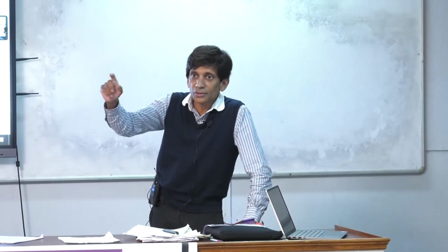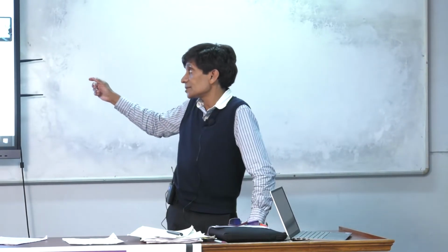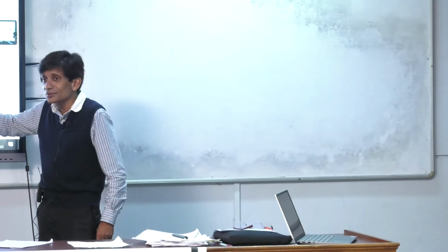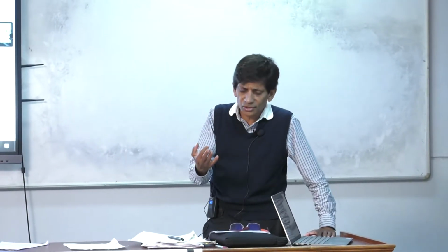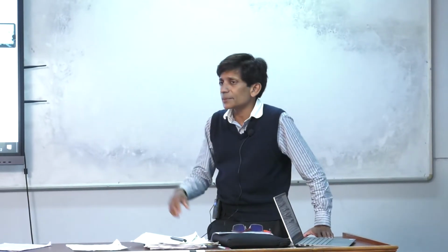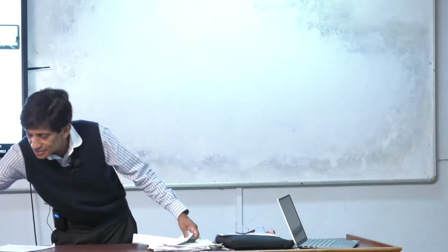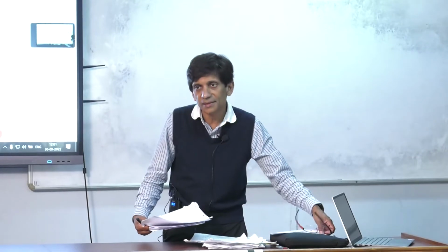Mass balance on the overall system, mass balance on one of the phases. You could have done a mass balance on the dialysate instead of the blood. It's more complex though because the dialysate you're trying to calculate things there. So it'll become mathematically more complicated, but you can do it, okay? And then you solve three simultaneous equations and you come up with the numbers, okay? So that question I put there on purpose. I thought it was a bit difficult, but on the other hand, it was one that kind of links up with what you probably learned earlier in classes, so I thought it would be interesting.